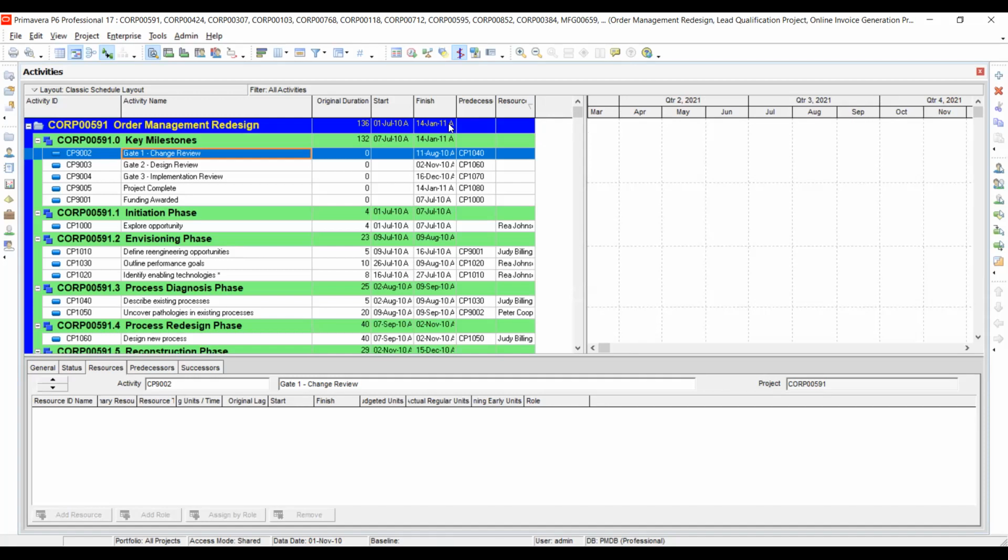Because when we've started on the rates and the resources, we need to digest it very well. For today, I wanted us to create a project, create the work breakdown structure, input the activities inside the work breakdown structure, and assign predecessors and successors. We've also assigned resources, but we're still covering more about resources.